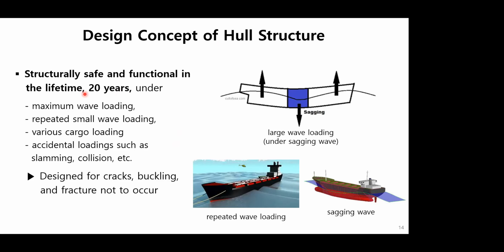Basically, hull is designed to be structurally safe and functional in the lifetime of 20 years under maximum wave loading and repeated small and medium-sized wave loading, various kinds of cargo loadings, and many accidental loadings such as slamming, impact, collision, etc. I'm going to talk about those loadings in more detail later.